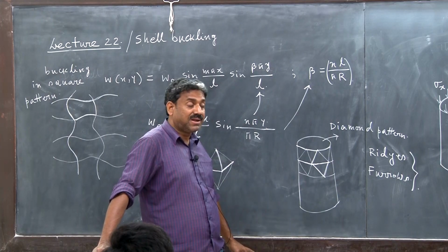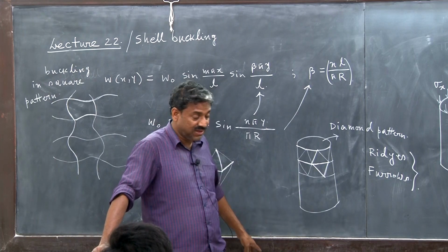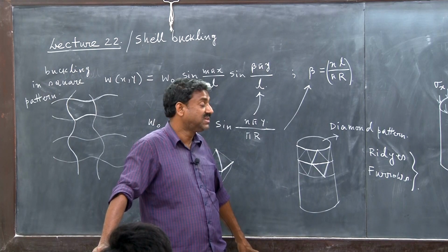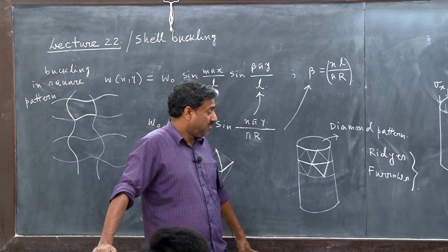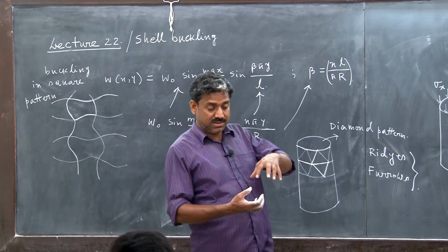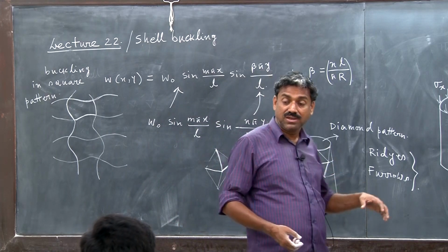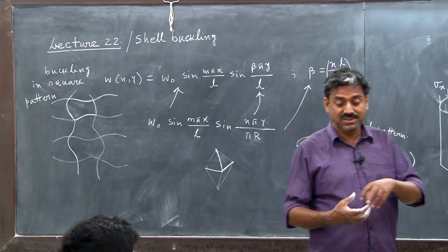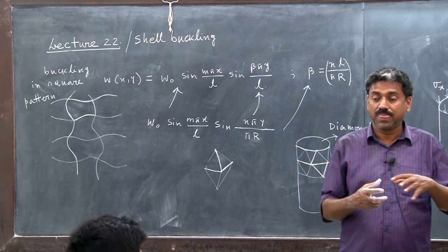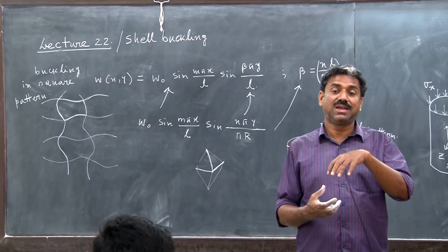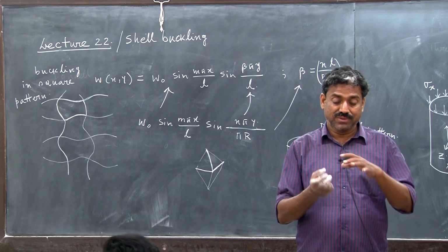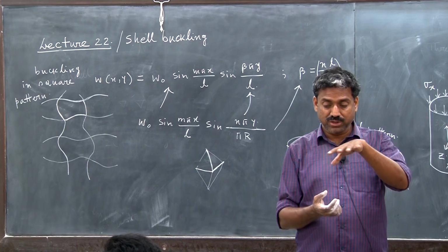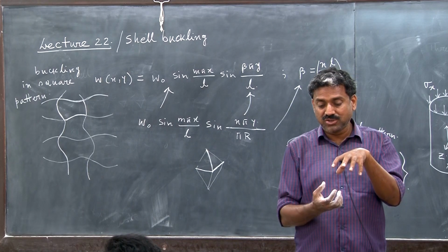And for this kind of pattern, you have to be careful to do this experiment. You will search on YouTube or in a book, you will see this picture. You have to take this cylinder and put a mandrel inside it, so that the cylinder basically rests on a mandrel radially. That means it does not go inward.